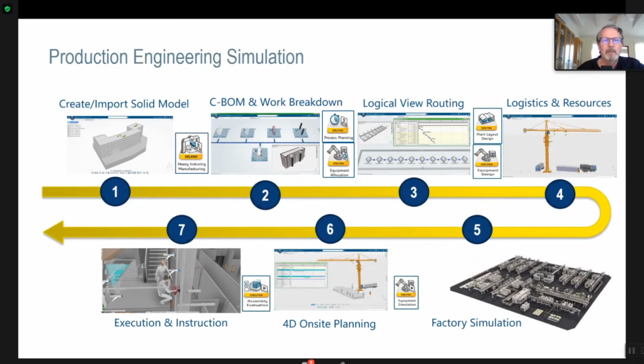In this data platform, we can preserve multiple file structures: the architect's preferred structure compared to the scheduler's structure, to the estimator's structure. In manufacturing, we do that with an engineering bill of materials, EBOM, and a manufacturing bill of materials, MBOM. So I'm calling this a construction bill of materials, CBOM. And from that, you want to create a work breakdown structure. Then you can connect the work breakdown structure to labor, materials, scheduling issues, and cost issues. So now it's got 4 or 5 different data structures that are all preserved.